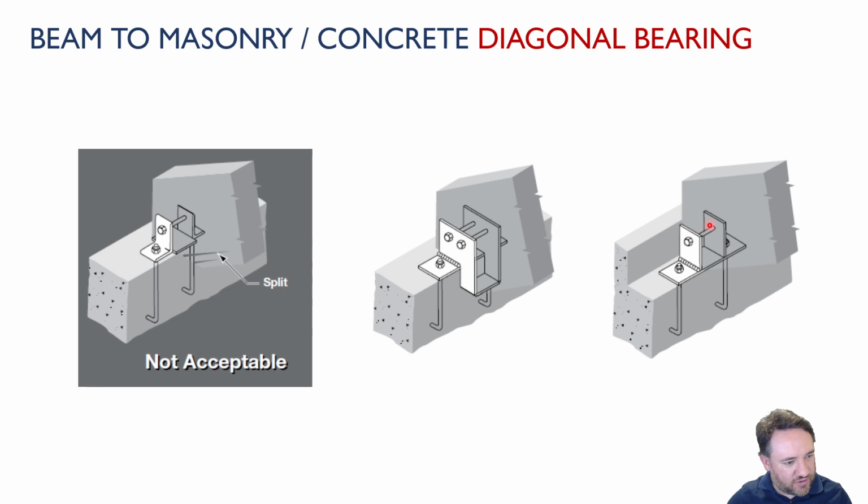And of course, another option is cut a notch out of the concrete, like design the concrete to have a lowered kind of sill here for sitting the beam on, so that I don't have to expose the bottom edge of this angled surface and make myself subject to these kind of splits. All of these pictures, by the way, are from the Introduction to Wood Design book from the Canadian Wood Council.